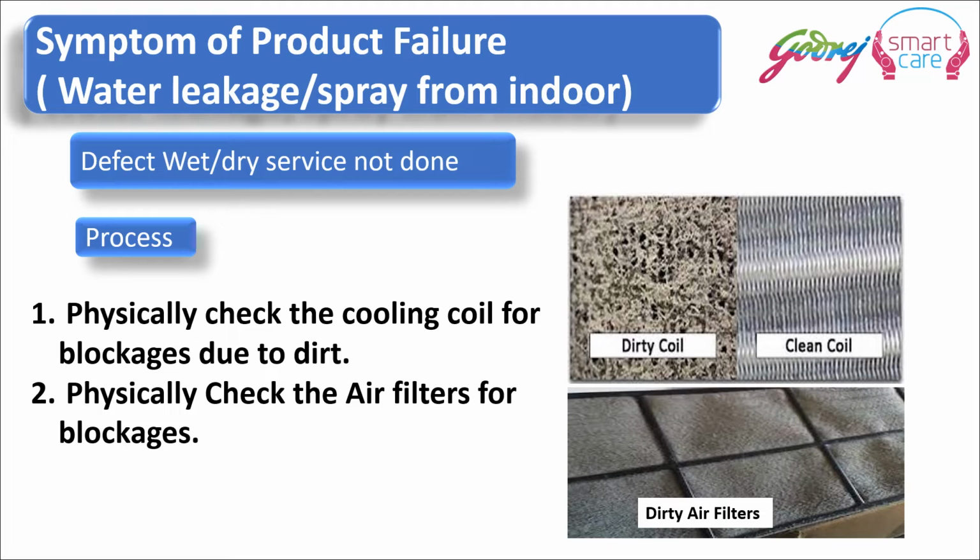These water droplets get entrapped and loaded onto this dirt, and when the dirt can hold no more water, the water droplets then start dripping from this dirt directly onto the blower, and when the blower runs, the blower impeller will take this water and throw it out through the grill into the room. So this dirty water is thrown out by the impeller into the room only because that water is not trickled down the fins to the drain tray, and it is dropping onto the running blower.